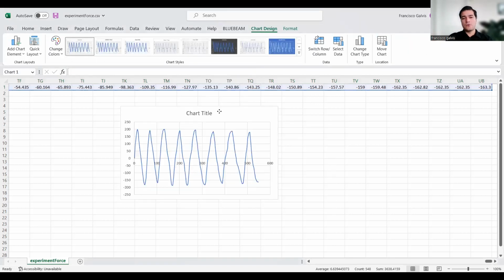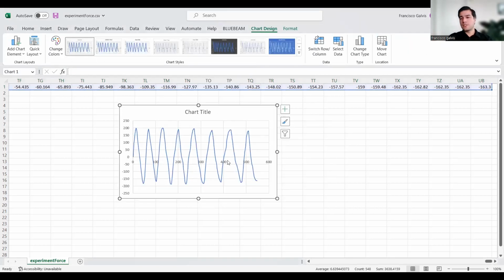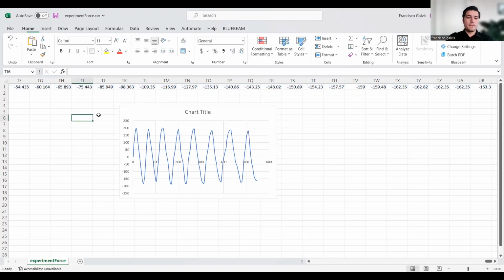And then here you can see, of course, how for each of those cycles we looked at before for the imposed displacement, we have a corresponding force, right? And you can see how they get to a certain value and then get saturated, because we are in that post-elastic response where you get a plateau in the response.